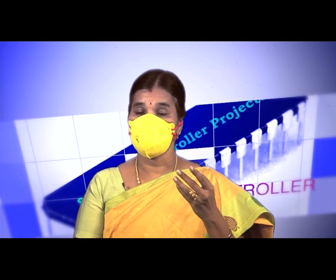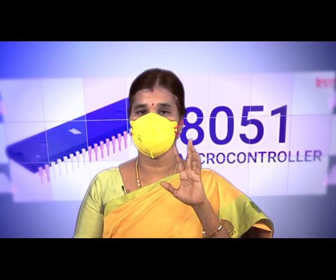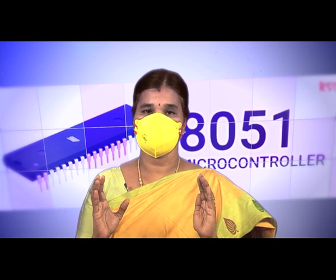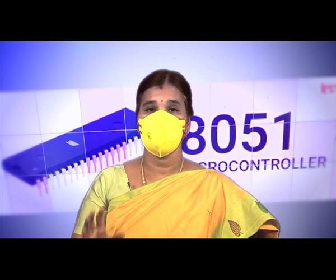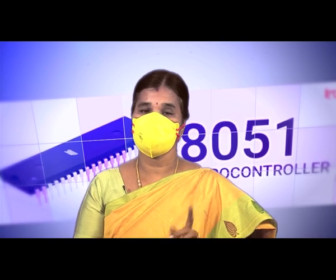Suppose I have 10 address lines, then 2 power 10 gives 1 kilobyte of memory. That defines the maximum capacity. How much data you can store in the memory is defined by the number of address lines. Each address will hold only 8 bits, that is, a byte. If both read and write operations can be performed, that is called a RAM.